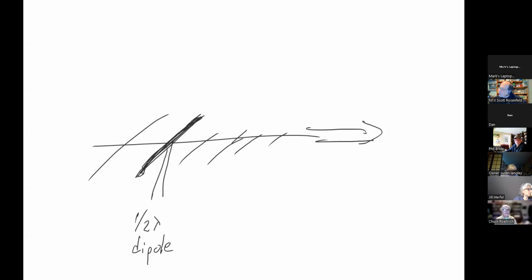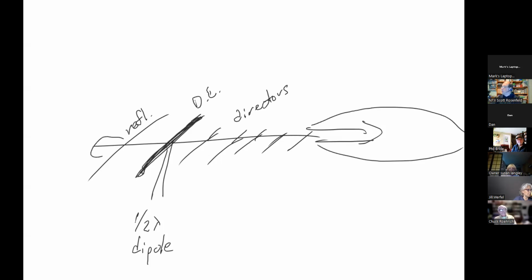So you would then make this one, this is known as the reflector, slightly longer, and these are known as directors. Those are slightly shorter. You would typically have one reflector and one or more directors, and they would basically parasitically resonate with the driven element. This is called the driven element, and direct your energy in the forward direction with only a little bit going out in the back. So it basically changes your pattern so that you have a much more concentrated signal in the forward direction.